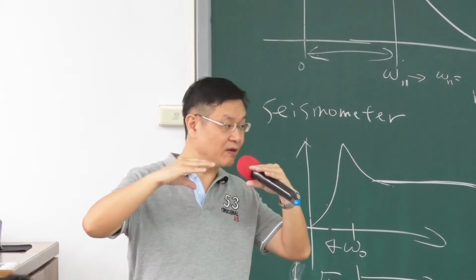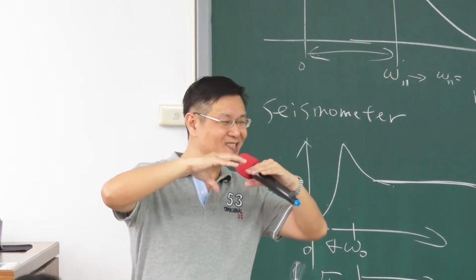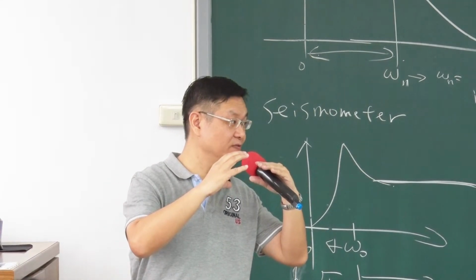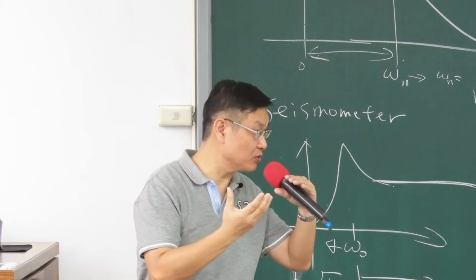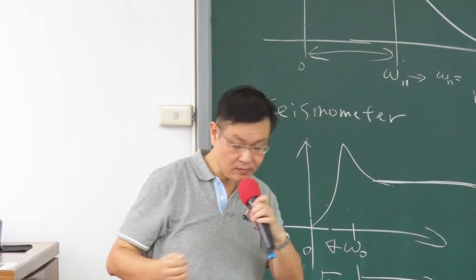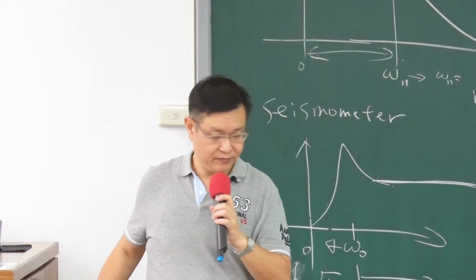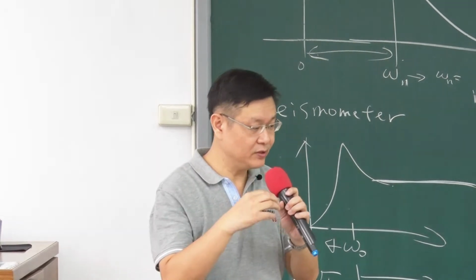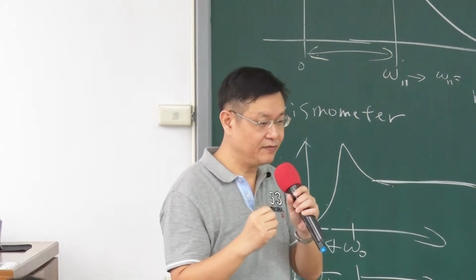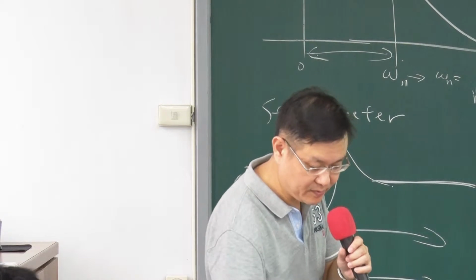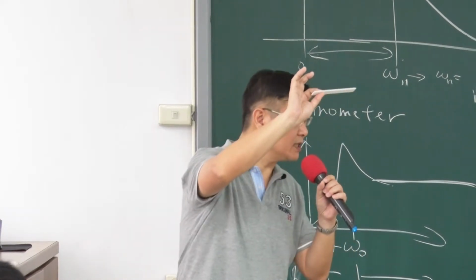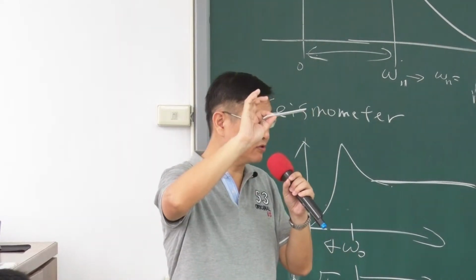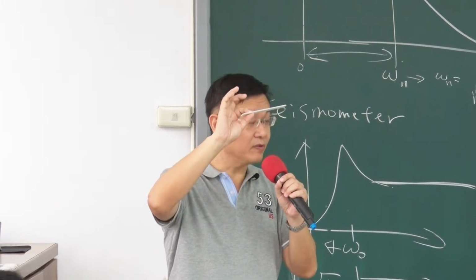So you have a special design of a structure. The structure can resist bending very well if you have a higher moment of inertia. For example, can I borrow a ruler? Does anybody have a plastic ruler? Yes, thank you. The same material, right? But you design a different structure. You have different moment of inertia.